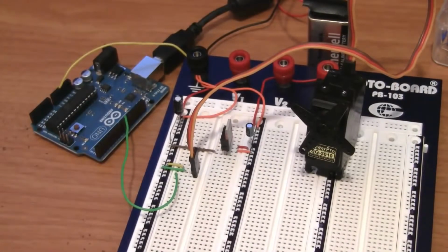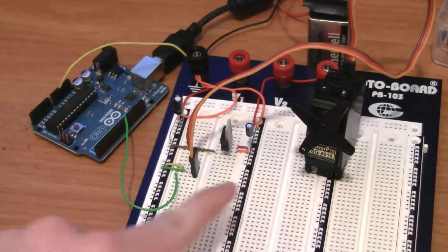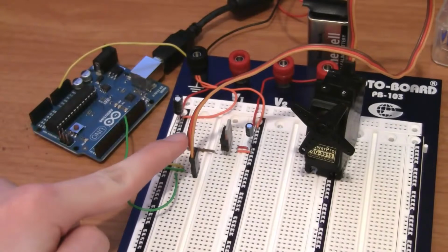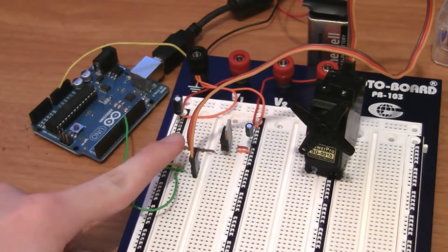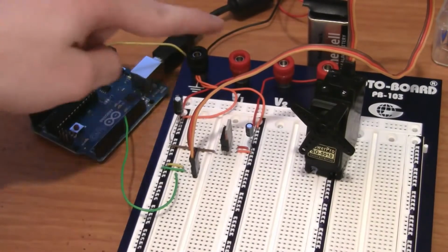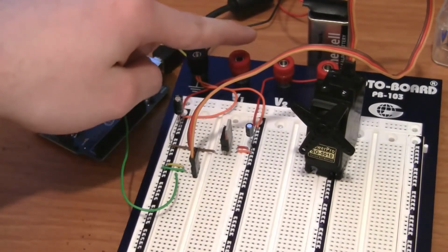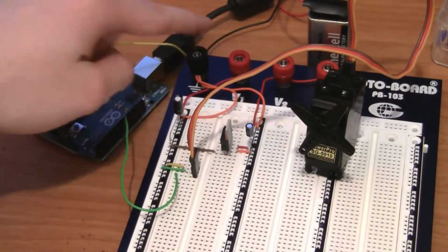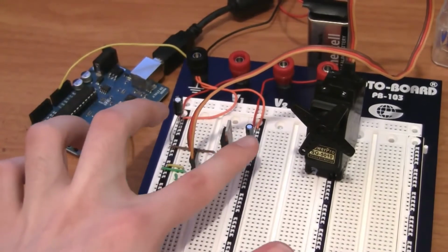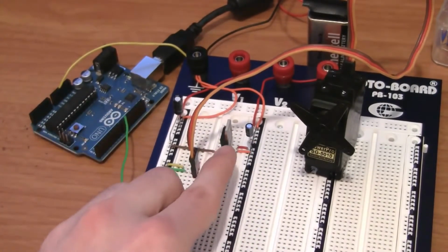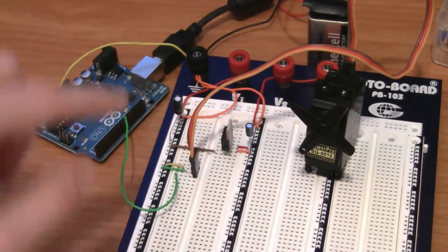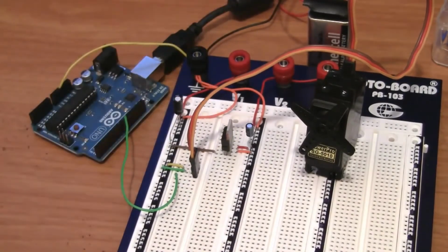Here we can see the circuit all wired up. You can see the servo motor here. It has 3 wires. The yellow wire goes to pin 9 on the Arduino, the red wire goes to its 5-volt supply, and the brown wire goes to ground. Note that I've disconnected the 5-volt wire of the Arduino from the board. The 2 5-volt lines should not be connected together because they're from different supplies. The grounds, however, are still connected through this lug. You can see the 2 decoupling capacitors here, and our 9-volt to 5-volt voltage regulator right here that's going to be powering the servo. We have a 9-volt battery hooked up to it.